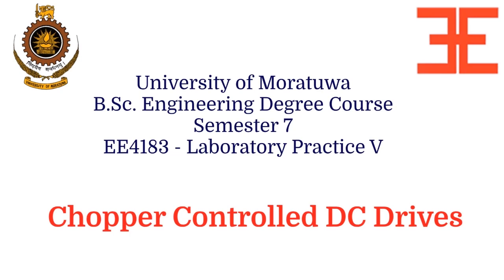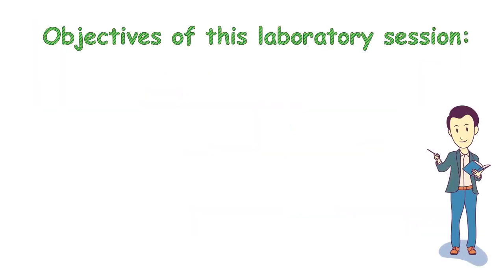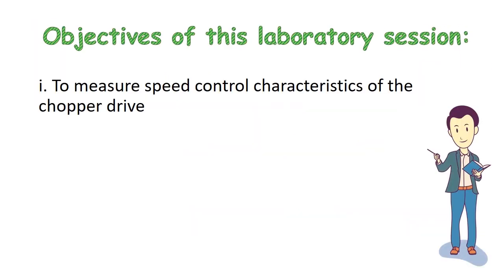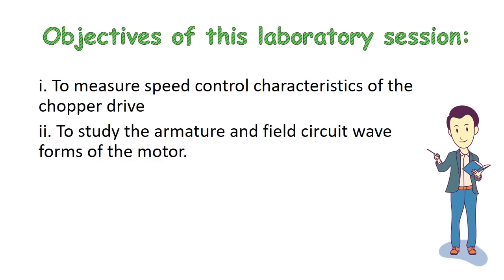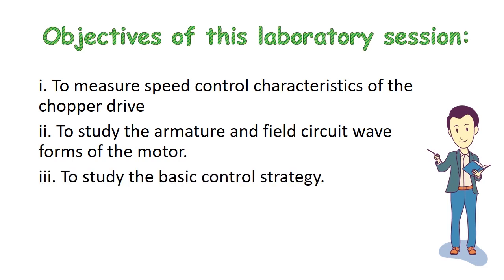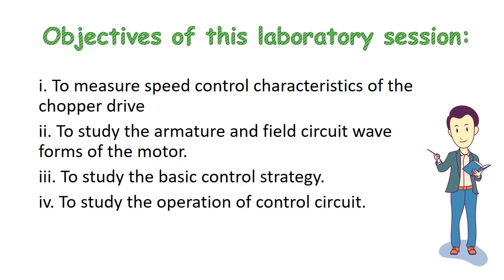First, let's identify the objectives of our lab session: to measure speed control characteristics of the chopper drive, to study the armature and field circuit waveforms of the motor, to study the basic control strategy, and finally to study the operation of the control circuit.